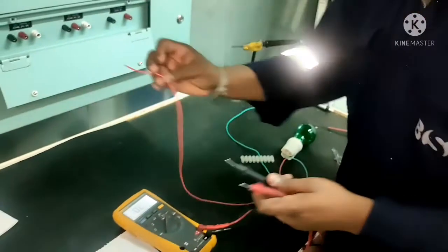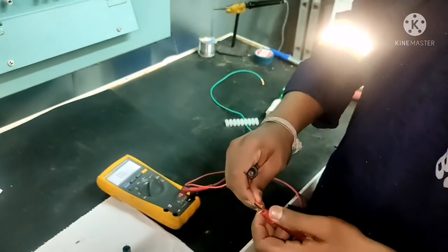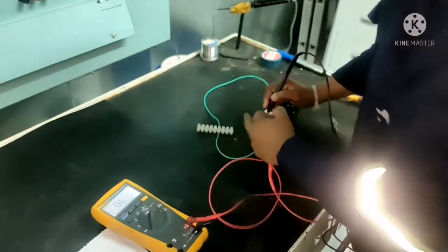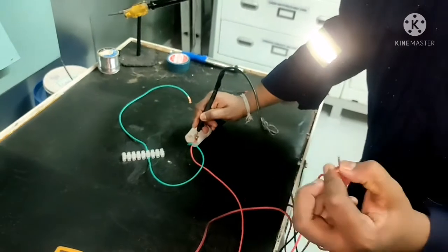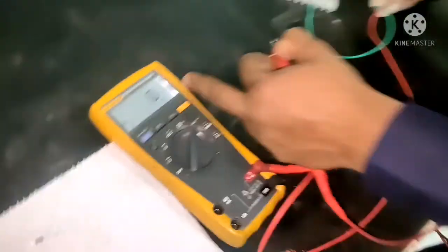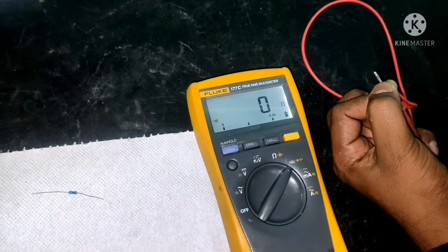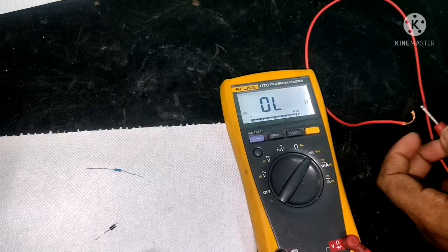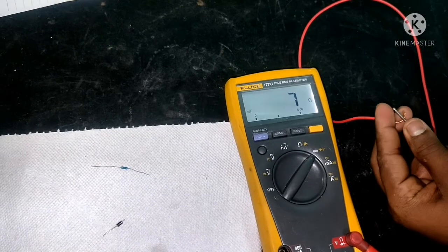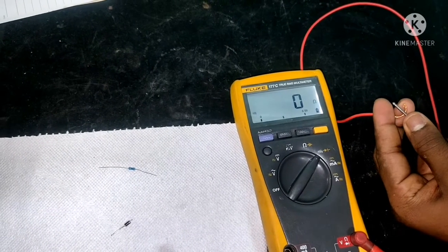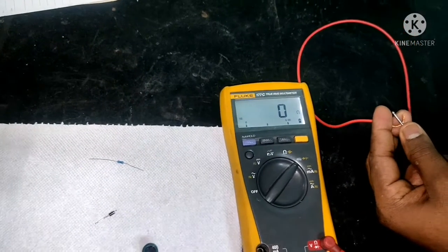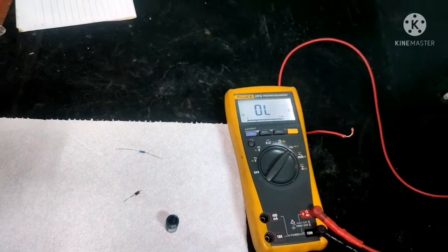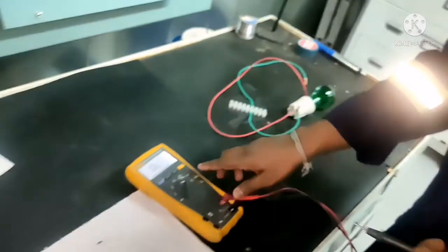Okay, now I will show you how to check the continuity of a cable. You first connect one lead to one end of the wire and the other lead to the other end. If you connect both ends, you have to get a value of 0. That means there is no problem in the wire. And if you remove that lead, you can see the open symbol in the display, which means the cable is not okay. Now if the value is 0, then it is okay. If you find the open symbol on the display, then that means there is some problem in your cable.